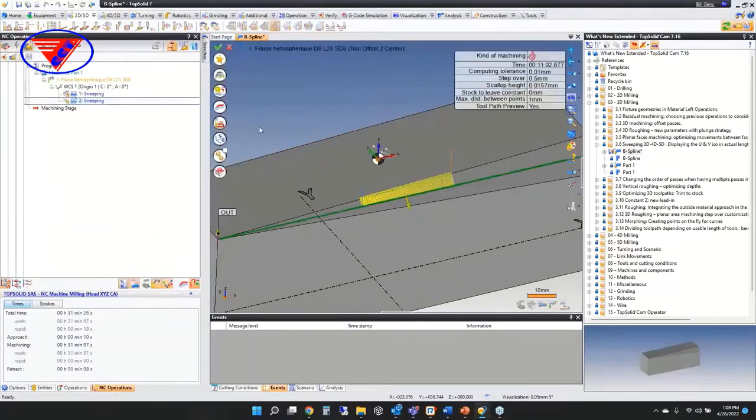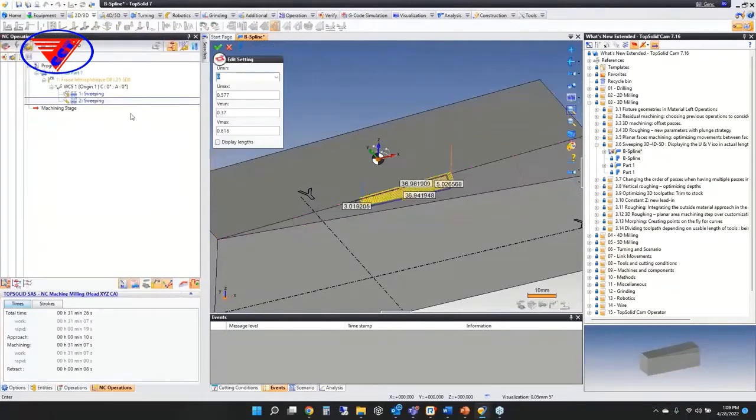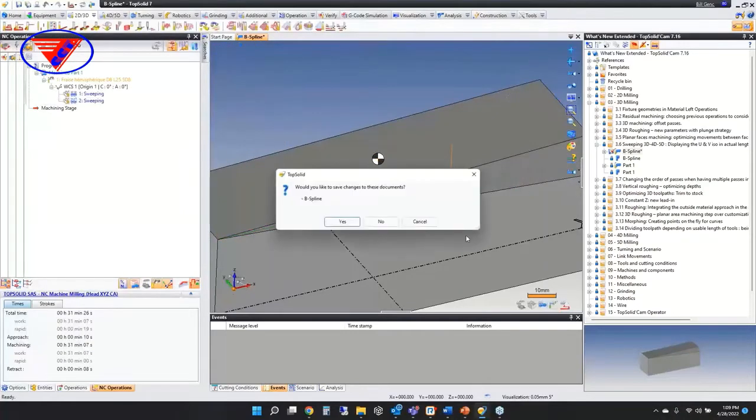That's not the improvement though. The improvement is that you can choose to show the length of the ISO curves. That's this thing right here. So this option is the improvement. It just gives you a length. It's not modifiable. You can't double click on these things. Okay? You can move them out of your way, but they will update as you move the ISO curves. Okay, so this way again, you have a better idea of the area that you're machining. Okay? Perfect.